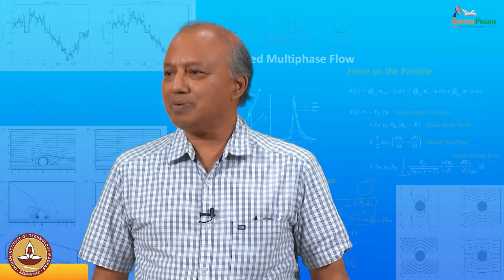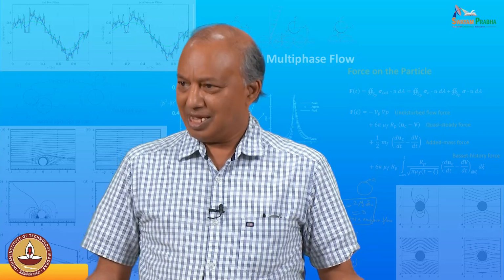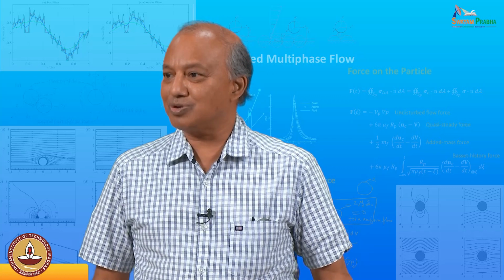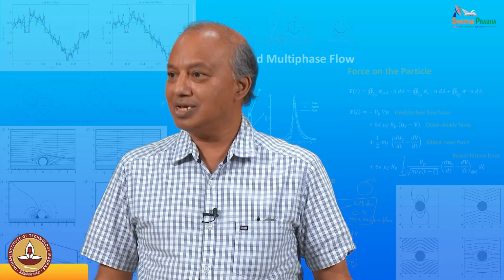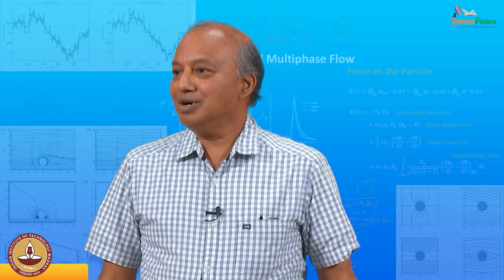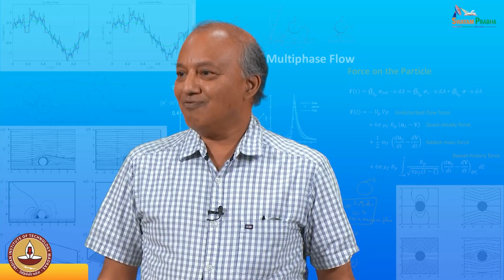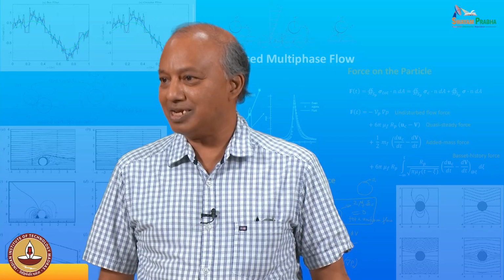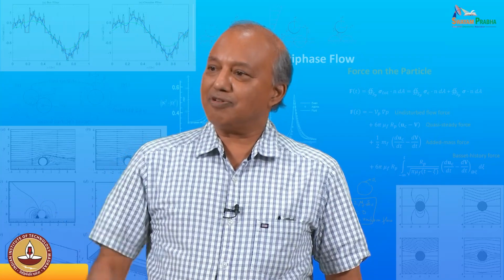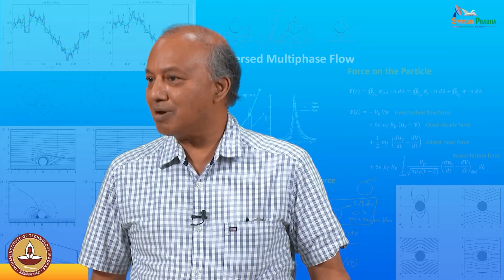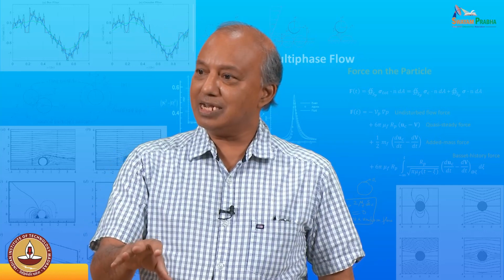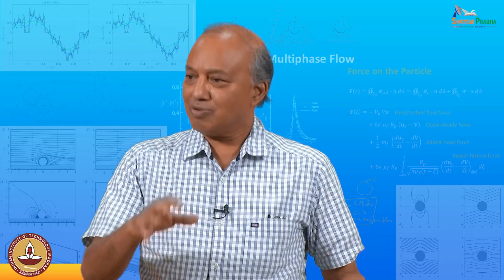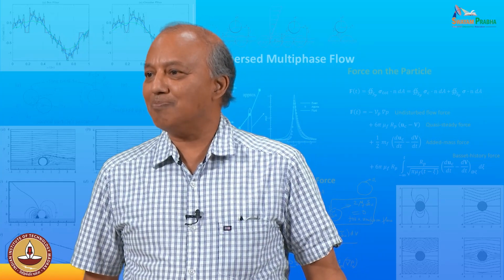Let us say 10% of the realizations had particles and 90% you saw fluid at that point. Well, right away you know that at that point the volume fraction of particles is 10%, because only 10% of the time you see it. So, you can move to a different point and do the same ensemble average. The ensemble average will tell you the probability of finding a particle there.